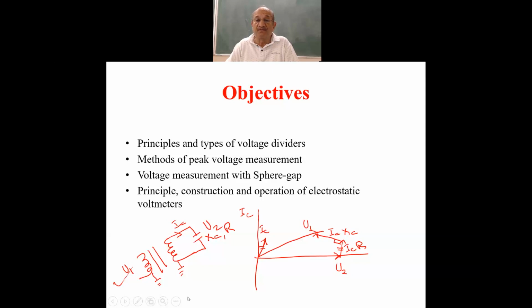This is very well known for open circuited transmission lines, because the transmission lines form a very high capacitance under this condition, and so the far end voltage is higher than the sending end voltage that you must have learned. So the technique of calibrating the primary side of the transformer would give you a misleading magnitude of applied voltage on the test object.